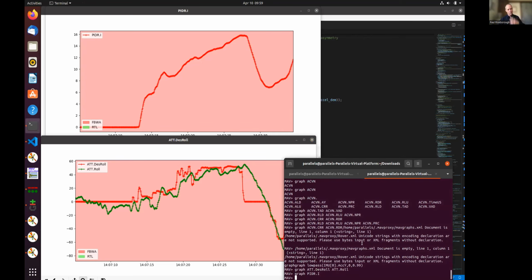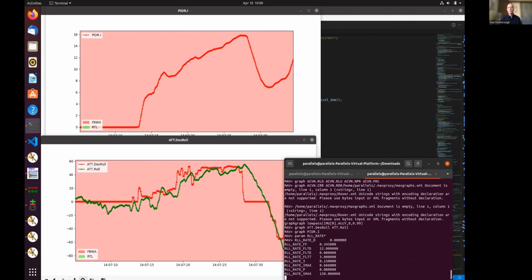Now I've seen this happen. This is the second log I've seen where this has happened for twin engined aircraft with not much yaw stability. They've got themselves into a situation where the I gain was just not fast enough, just not enough I gain. If we have a look at the parameters for this log, I think it was, you can see the I was set to 0.15. Yeah, that hasn't had an auto tune. No, it certainly hasn't.